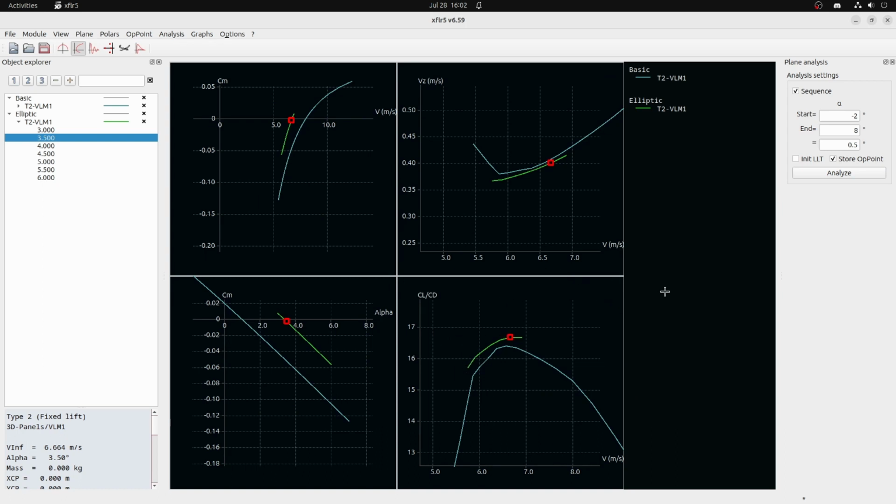Now, another thing we could look at is the location of the neutral point of the wing to help us set the CG. What we can do is to try moving the weight forwards and backwards in this simulation until the pitching moment is a flat line with no increasing or decreasing slope. This is a point for the aircraft where if there's a small disturbance, the plane doesn't try to either return to the original flight or to become totally unstable.